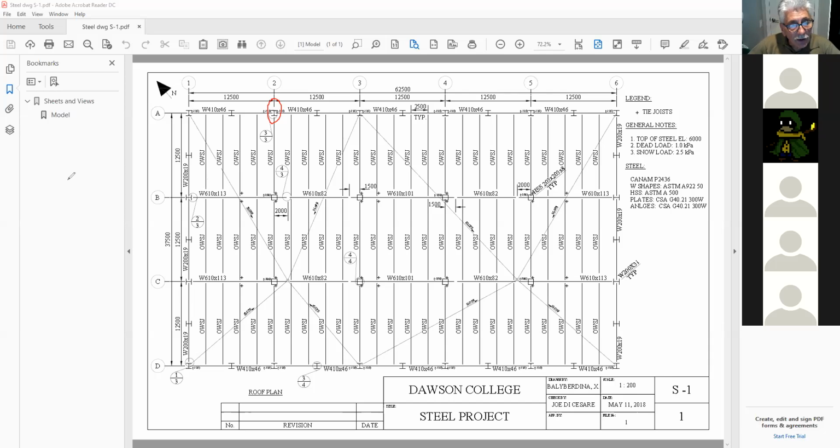And like I said this morning, guys, we saw that when we're welding these two angles back to back, like this was one of them, here was the other, like this. And then, let me change colors, let me put some purple. If you notice, it was welded 2 times the thickness of the weld here, and then it was all the way welded down there, 2 times the thickness over here, and all the way down there.